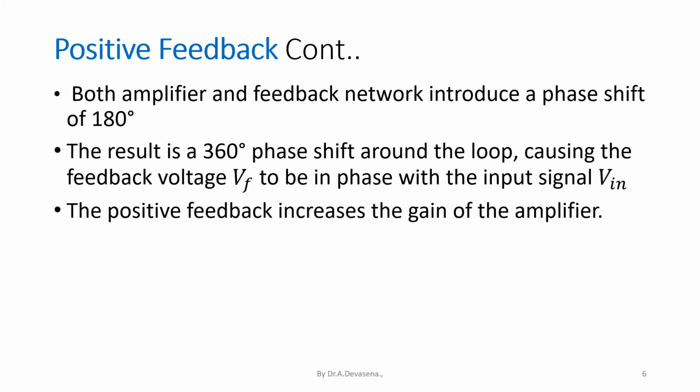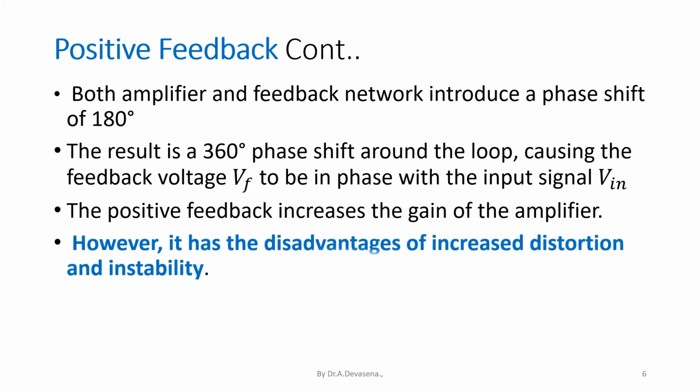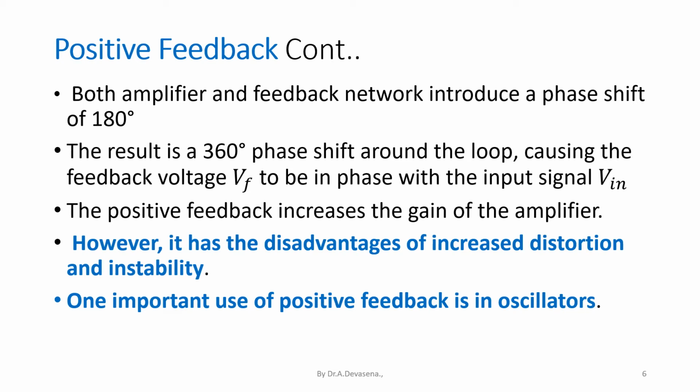The positive feedback increases the gain of the amplifier. However, it has the disadvantages of increased distortion and instability. One important use of positive feedback is in oscillators.